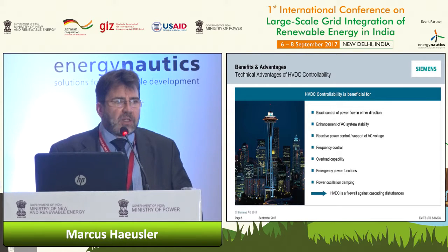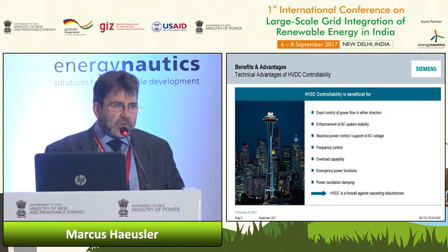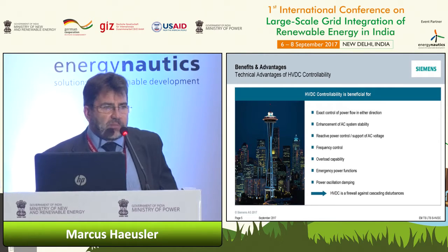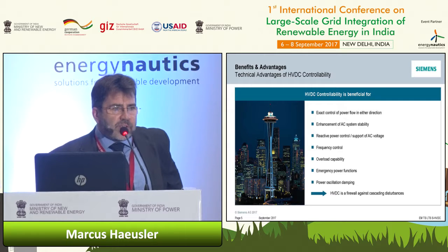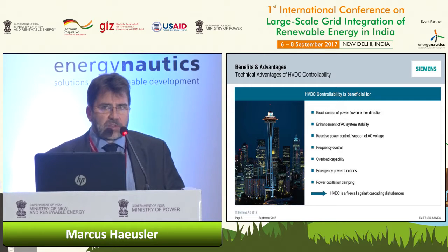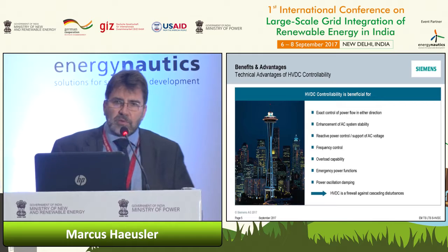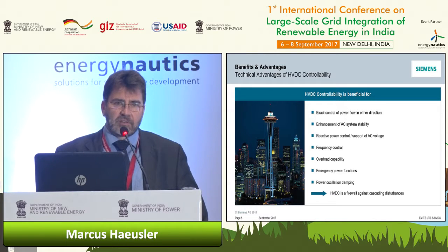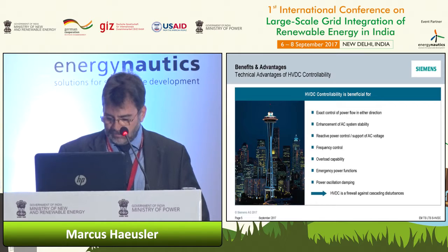In parallel, HVDC can also control the voltage by changing the reactive power demand, and especially the new technology, the voltage source converter technology, is very powerful to have a fast way, and this is acting similar to a STATCOM in this case.